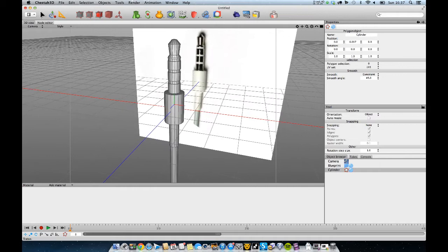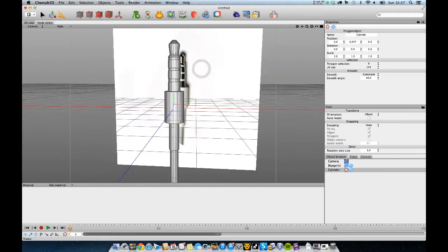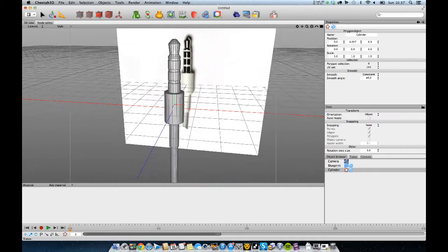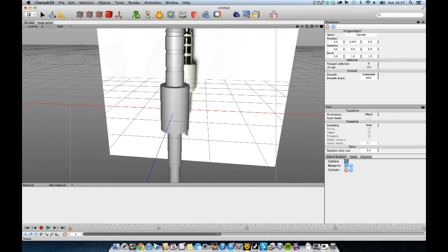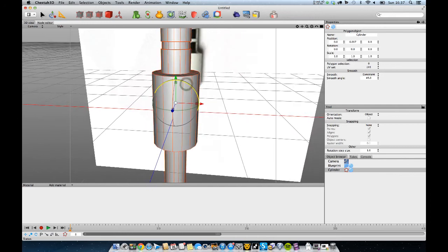Right, the next problem we've got is when we throw a subdivision on here, it's going to absolutely obliterate what we've got. And that looks nothing like what we want. So get rid of that subdivision in a second. We're going to need a lot more ring cuts to kind of protect these edges. So anywhere we want a hard edge, we're going to need to either use a crease, which I don't really use, or we're going to need some strategic ring cuts placing.